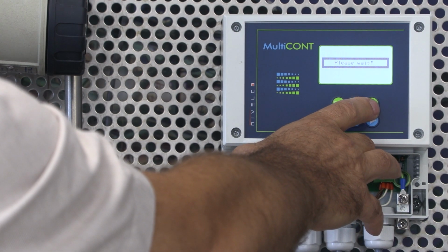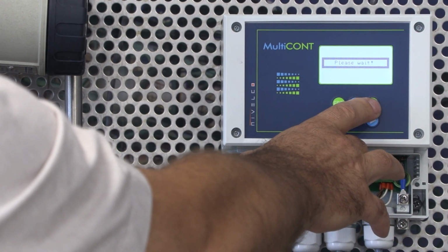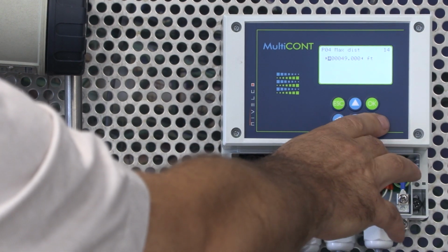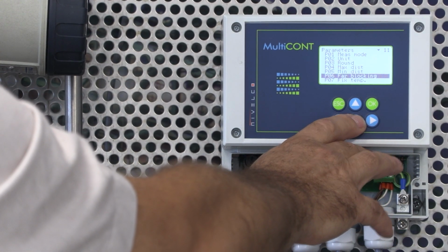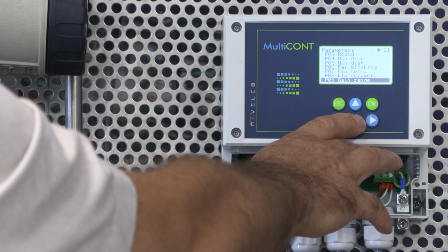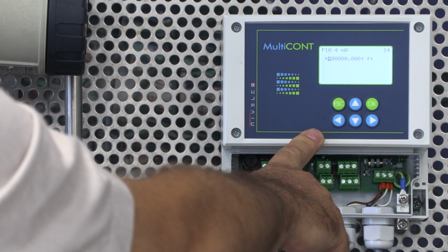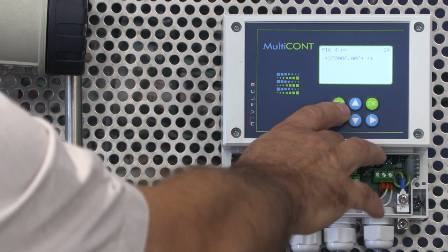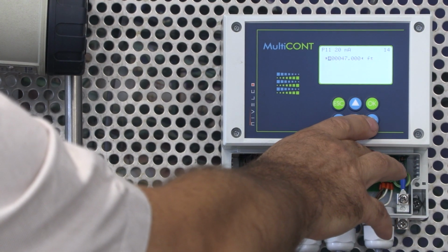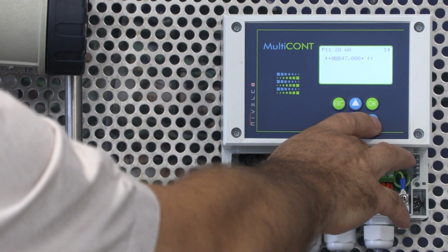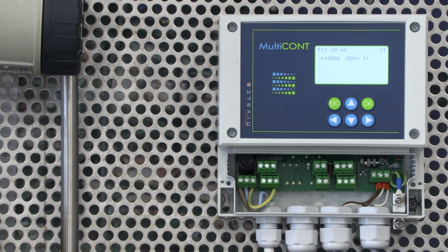The rest of the units are automatically set to US standard. For example, maximum and minimum distance are displayed in feet. The 4 mA signal is assigned to the 0-foot mark. The 20 mA signal is automatically assigned to the 47-foot mark. The difference between this and the maximum distance of 49 feet is the dead zone, which must be observed.